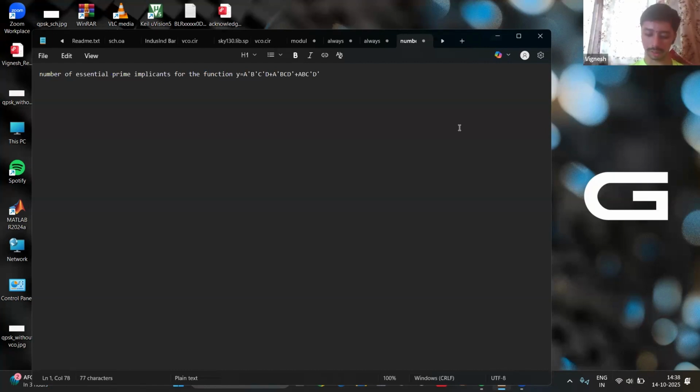Don't care condition comes, right? No, no, no. There is no don't care condition. Only these three terms are high in the K-map. There are blanks, so they can be X or 0, correct? Yes.